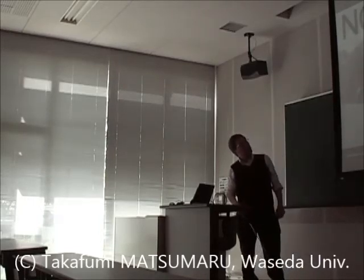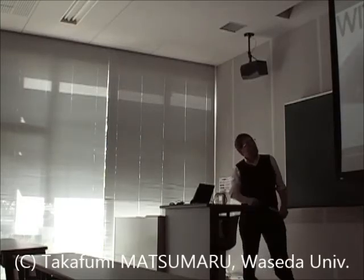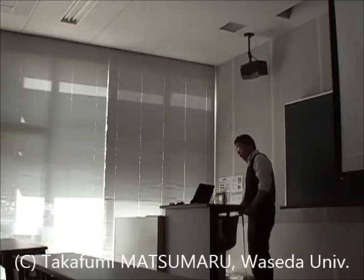As you can see, without the VGs, the telltales are swirling all over the place from the circulating currents in the separation bubble behind my windshield. With the VGs installed above the middle section of the window, we see a huge improvement. This theoretically reduces pressure drag, however it does increase lift at the rear wheels, which reduces traction.